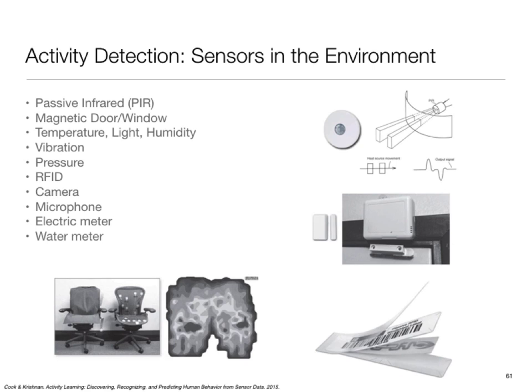You do it. But also, A to D converters typically allow you to simply tell them to sample at this rate. Then internally, the A to D converter has a timer, basically, and it samples, and every time it has a sample, it puts it into a buffer and raises an interrupt or something like that. So in which case, you don't have to maintain the timer. But they're basically equivalent. It's just how you're structuring it. But also, quite common is simply for you to do it in software.